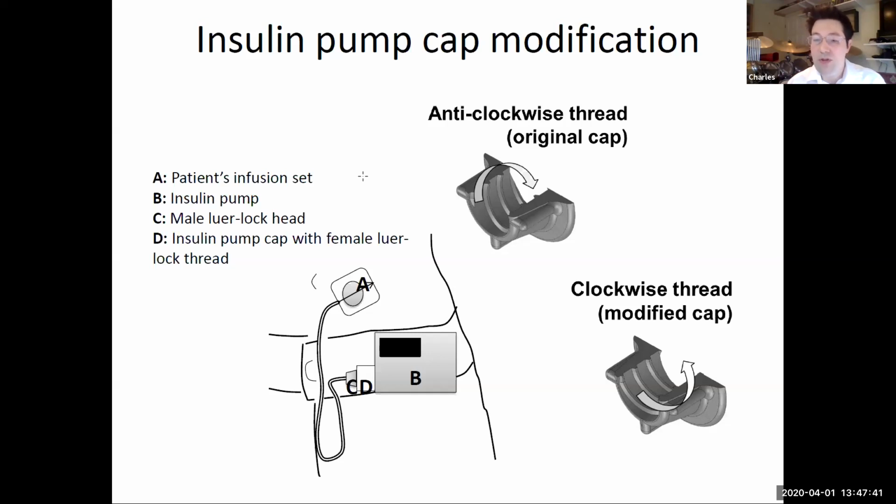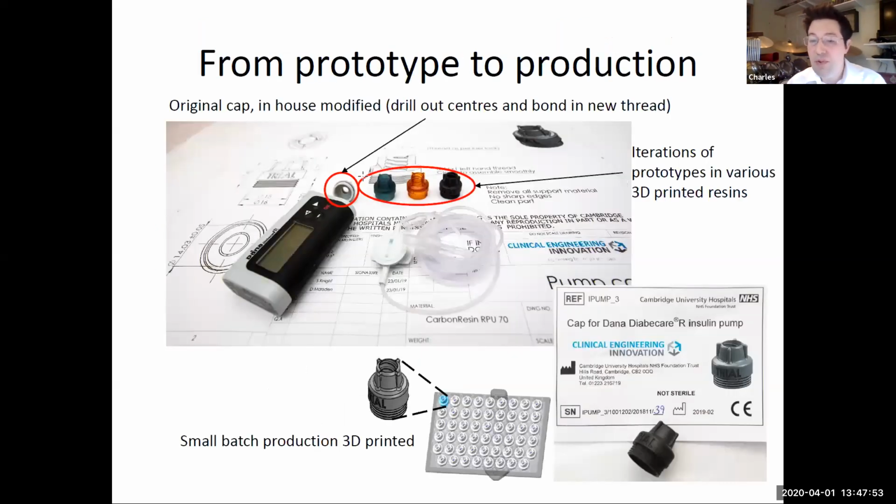As a result, it was a very simple modification. Just take the cap off and then put a new screw thread in. The original ones were literally put on a lathe in the workshop upstairs, drilled out and a new thread fitted.